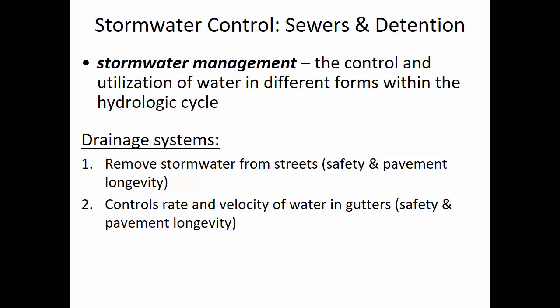The inlets have to be designed so that the water that's flowing in the gutters has enough opportunity to get down into the pipes, and so there's a certain system that we can use to size the length and width of the grates. They've even gone so far as looking at the angle that the grates allow the water to flow into the catch basin. And so the next priority is trying to preserve the longevity of the network.